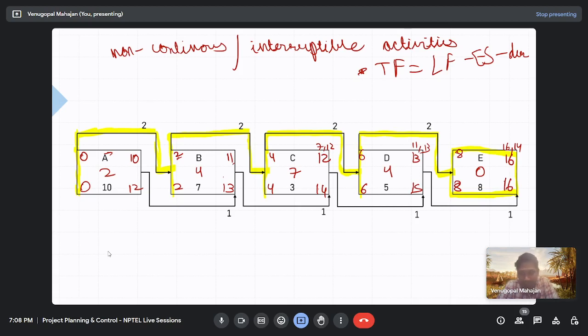The PDM, as per me, is giving the actual condition of the activity, whether its start is critical or its end is critical. According to that we can shift or make certain changes. Because it is telling you if the start or finish or the whole activity is critical, that gives you a better idea for control, right? Yes, sir. It is giving more information than CPM, sir.